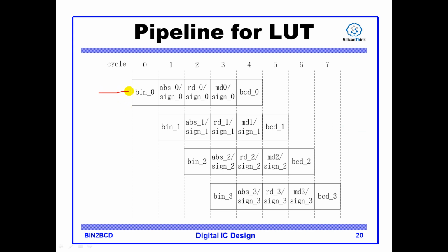So you can say for pipeline, you will divide the whole operation into several segments and insert a register between each segment. And from the view of one cycle, different inputs will be in different calculation stages.